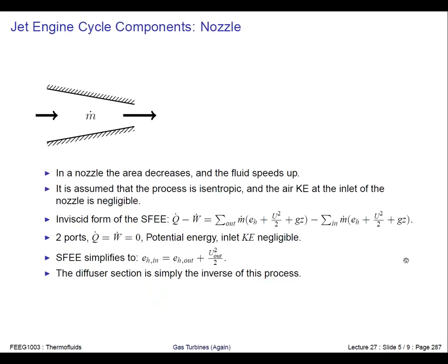And how do we do this? So we covered this in the previous lecture. Just to reiterate, we've got 1 nozzle and 1 diffuser. So for instance, if we're after the nozzle, then we neglect the kinetic energy here, but the kinetic energy on the outlet is the thing that we're after. So therefore the steady flow energy equation simplifies to this. We covered this in the previous lecture.